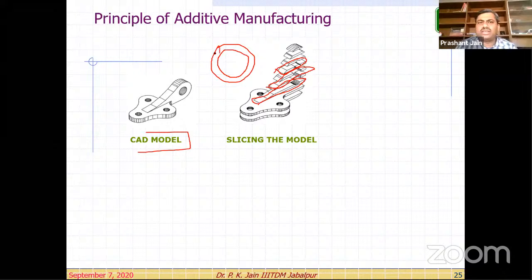And in between, this material has to be solidified or deposited, right? So that is the part we are going to fabricate. The point I want to make clear is that we need to solidify this contour material, right? So cross-sectional information needs to be collected, and after that, we need to deposit the material accordingly, right?